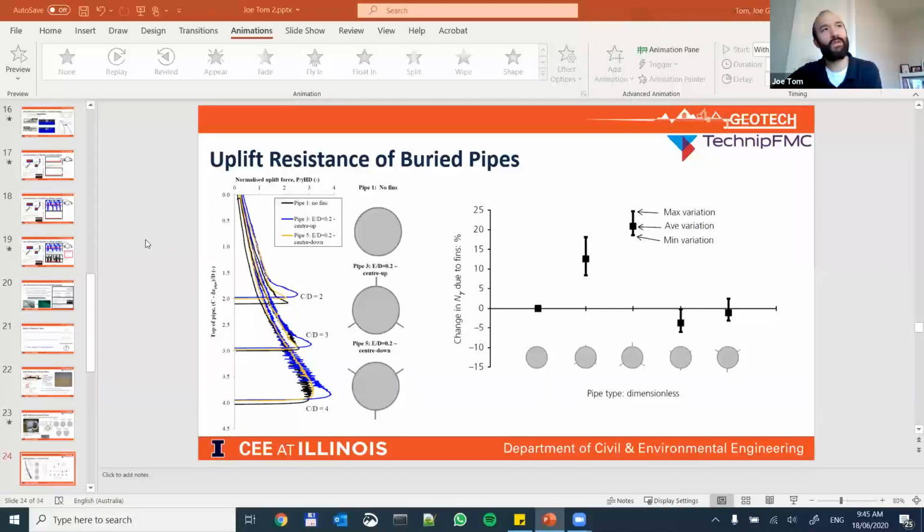But I think the main thing we should consider there is maybe more so the crushability and the compressibility of the carbonate sands. So in terms of especially the displacements, which we haven't really talked about here, you would expect potentially a condition where you start to get crushing of the carbonate sands, which you're unlikely to get in the silica sands. And so that would probably affect things.